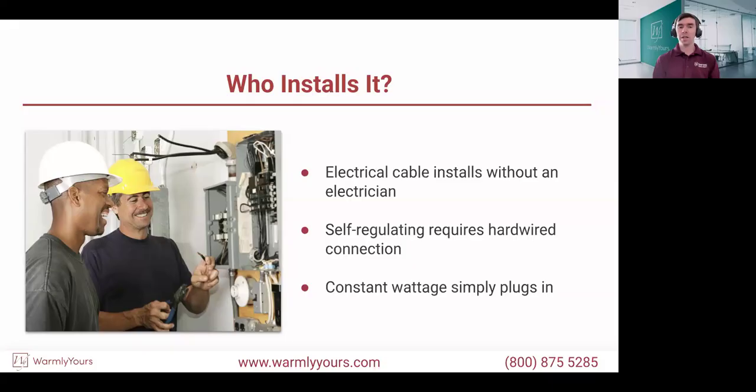Yeah, and I like how this slide connects a little bit to what you already mentioned before, Mary, about the power location. Let's say you have a separate party just getting your cable installed, say a roofing contractor. You still want to get that feedback or insight from an electrician about the power locations, like where the outdoor outlet will be planned for if it's constant wattage, or if it's a self-regulating cable, where the best locations are for the start point or junction boxes.